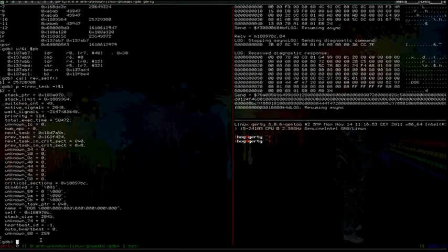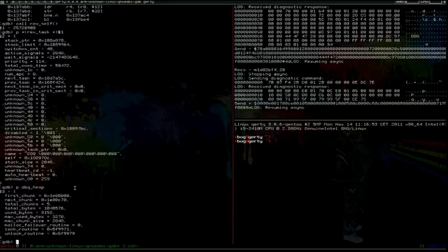So as you can see, you can do the same thing for the heap. For example, my debugger has a separate heap, so you can inspect structures very easily. Here you can see that I'm really calling this function in the context of the dog task. You have the name in the field directly in the task structure. So now for breakpoints.